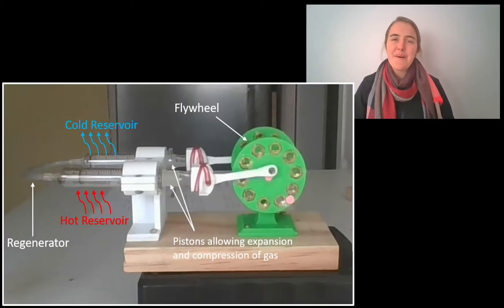So first up, what is a Stirling engine? A Stirling engine is a type of heat engine. It generates work by heating and cooling a closed volume of gas by moving the gas between hot and cold temperature reservoirs. These reservoirs are air chambers with pistons that are connected to a flywheel setup. The pistons cycle 90 degrees out of phase with each other to allow the air to move around as needed to create work. The Stirling cycle is best displayed by its theoretical pressure volume diagram.